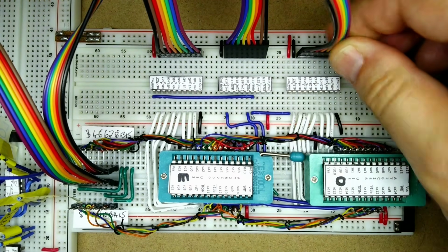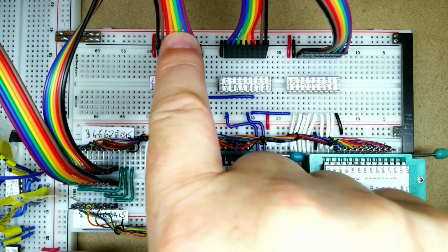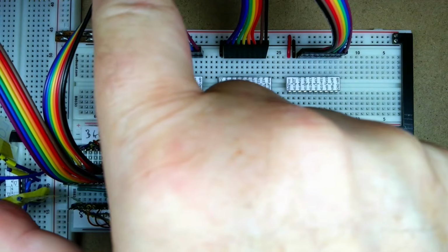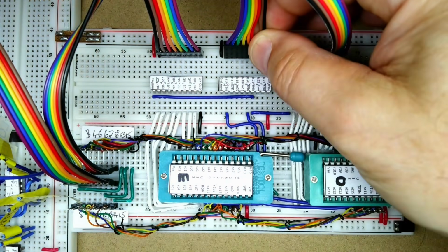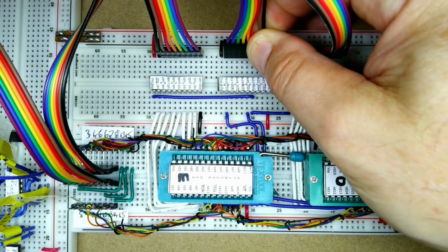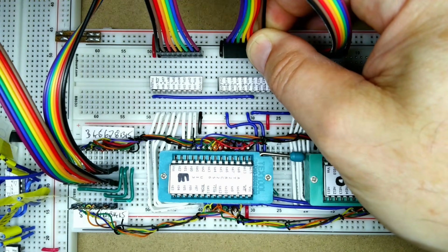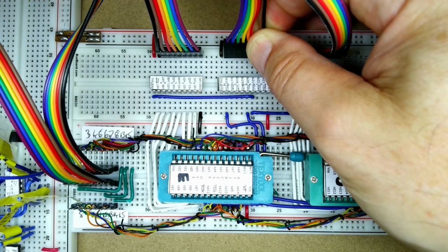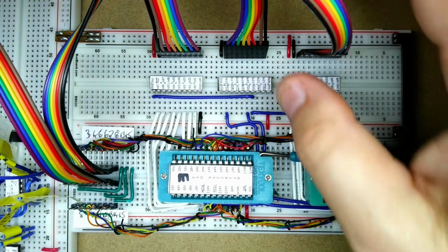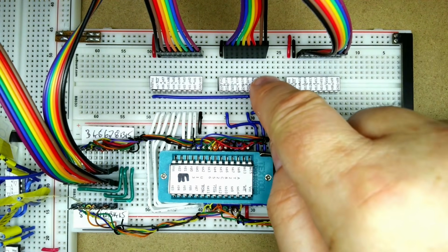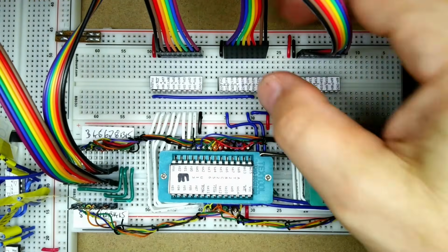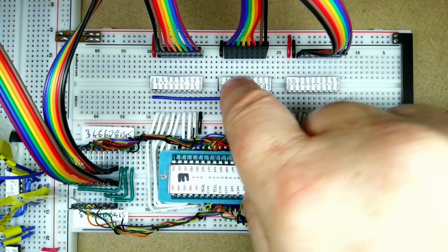We'll have a look at that in a minute. This one is the SD0 to SD7, similar to the one over here. And this one has to go to the latchable address 17, 18, 19, 21, 22 and 23. Then LA20 is a special case that we covered earlier, and that goes off to a different chip. And then the SA16 is also connected there.